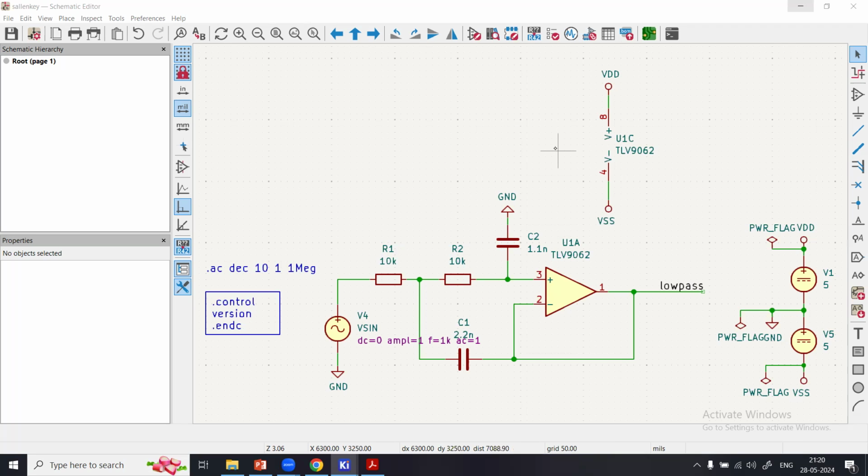And we also saw its comparison with the passive type of filters, which are implemented with mere RC components, or a combination of op-amp and the RC. But in this particular Sallen-Key type, we still use the RC combination along with the op-amp, but the difference lies in the arrangement of these components, as you can see, and I am going to explain in a moment, this arrangement right over here.